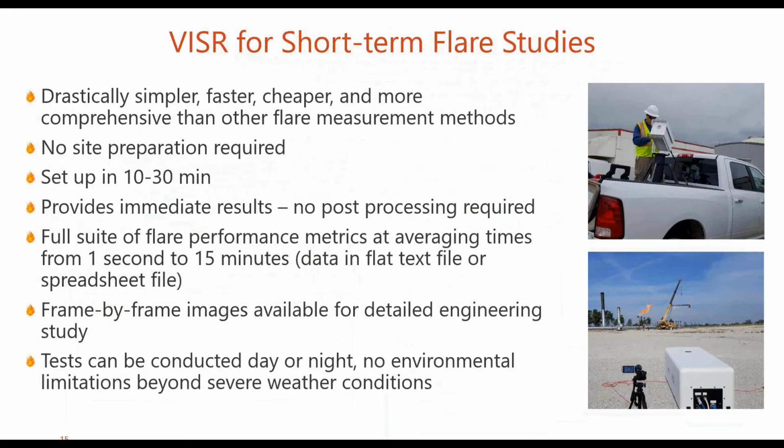We can also use this device for short-term flare studies if you have a need to measure flare performance to support a permitting effort or a performance test for a new flare, or just to learn more about the emissions from your flares or GHG emissions inventory, whatever the need may be. This device is well suited for that application. It can be set up in 10 or 15 minutes, and we're taking data, and there's no post-processing required. You get the immediate performance results.